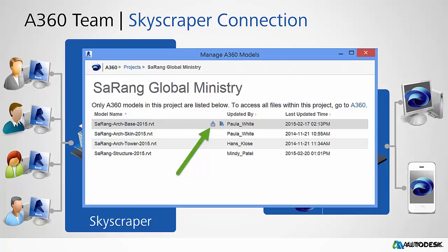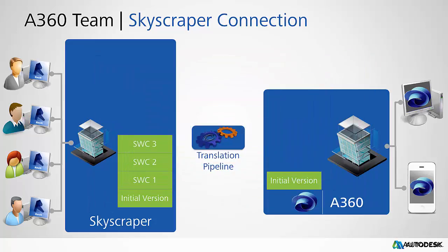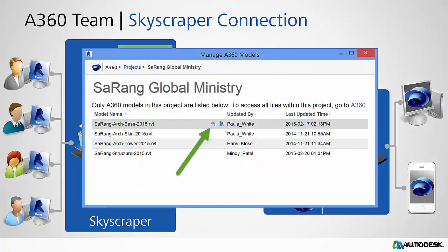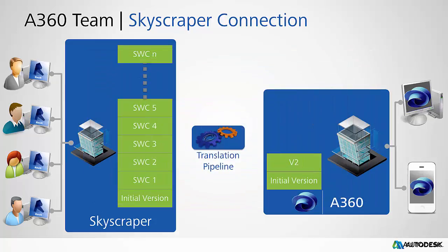When they sync to central, it will go to the Revit Collaborate environment, but then you have to push it to A360 should you want it to go into the Team Hub. So maybe we've done 3 sync to centrals. We can then push it into the A360 environment, and we can see version 2 has appeared. The users go through, make their data changes to the design, push through to the 360 environment, the team environment, and then this will come up as version 3, and so on.